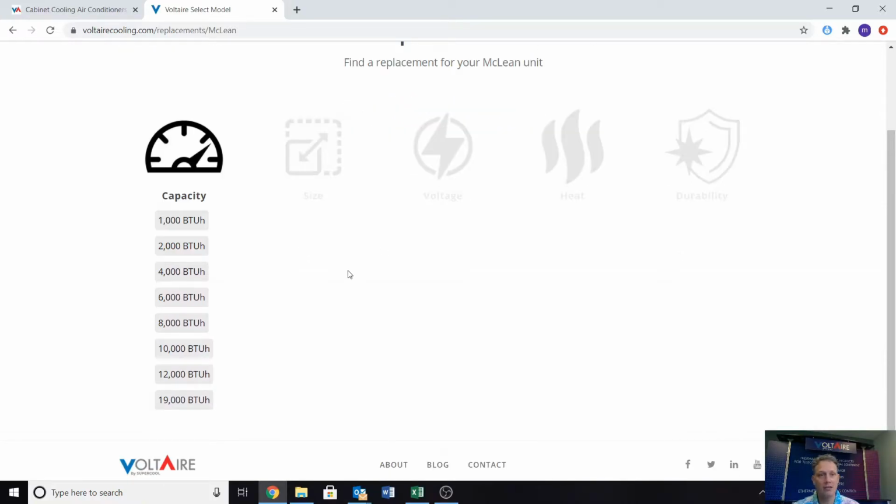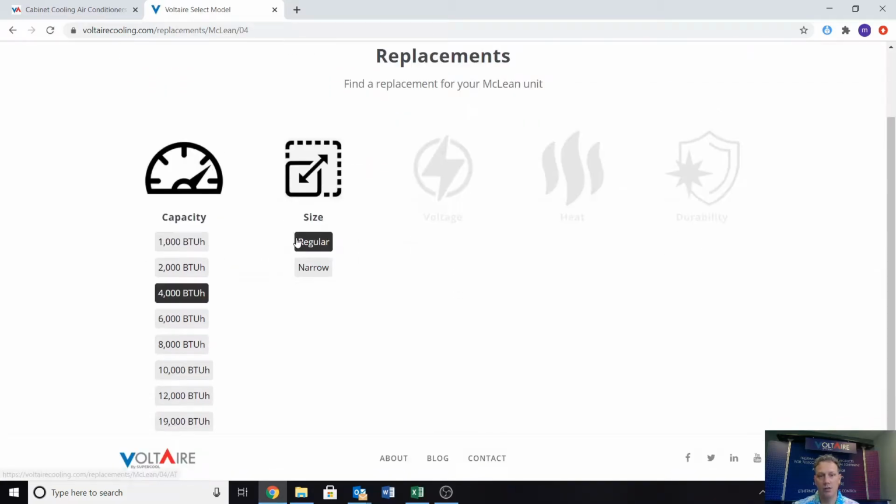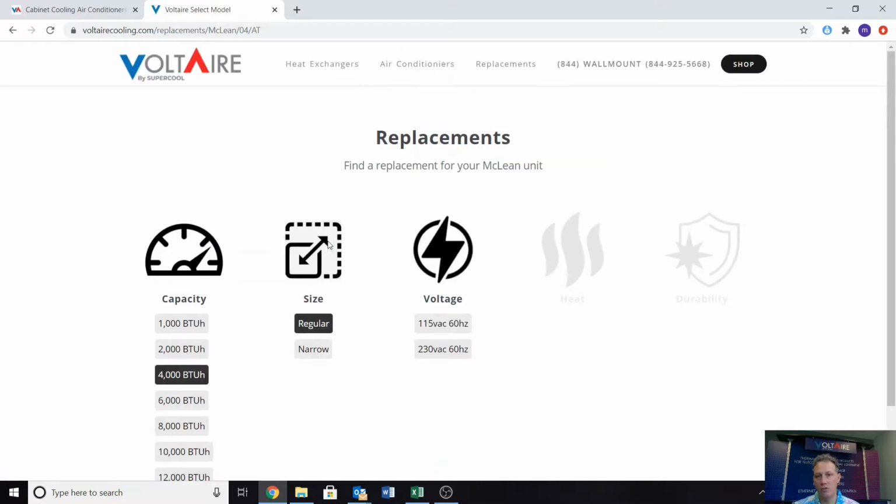That will immediately take you to this page, which the very first option for you to select is capacity. So on that data label that I was just talking about, there'll be a BTU. For the purpose of this video, let's just say you're working with a 4,000 BTU unit. You'll click on that. The next two options are regular and narrow. What that is in reference to is the width of the unit. So there's a narrow series for a lot of fractional tonnage air conditioning, and then the regular is just your standard width. I'm just going to say you've got a regular unit that you need to replace.